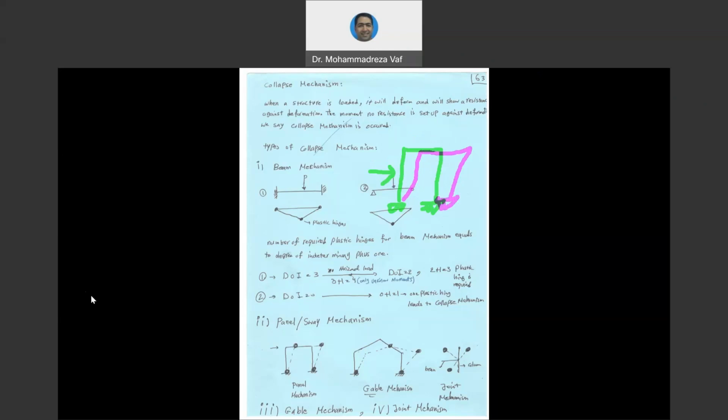Okay, one of the hinges, you need to have again four plastic hinges, and one of the hinges can be here, another one can be up here, another one can be here, like another one can be here. So these hinges basically occur at the location of maximum bending moment. And you will see in the next examples that we are going to solve how we can determine the location of these plastic hinges. But regardless, the load is at the beam or column.